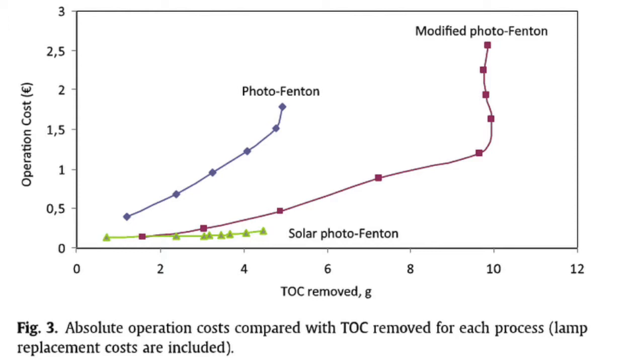This finding is due to the low efficiency of hydrogen peroxide when sample molecules have been degraded. More reagents are needed to continue the mineralization process, and in contrast, the costs gradually decrease in the solar process. For higher rates of TOC removal, the solar process becomes cheaper.